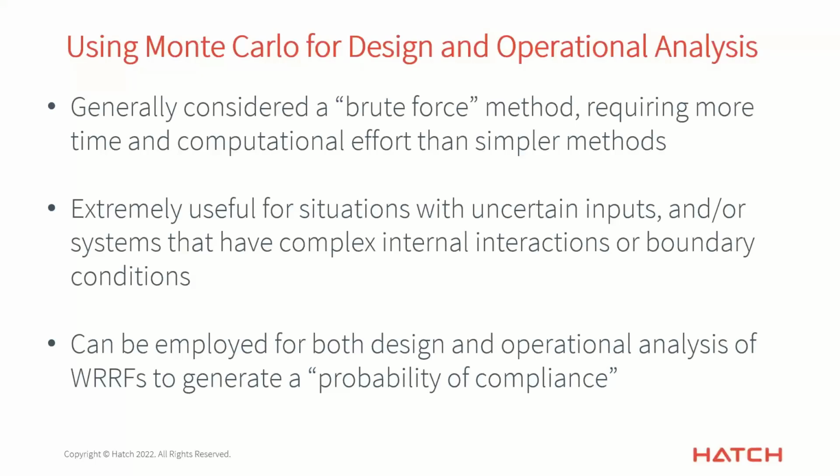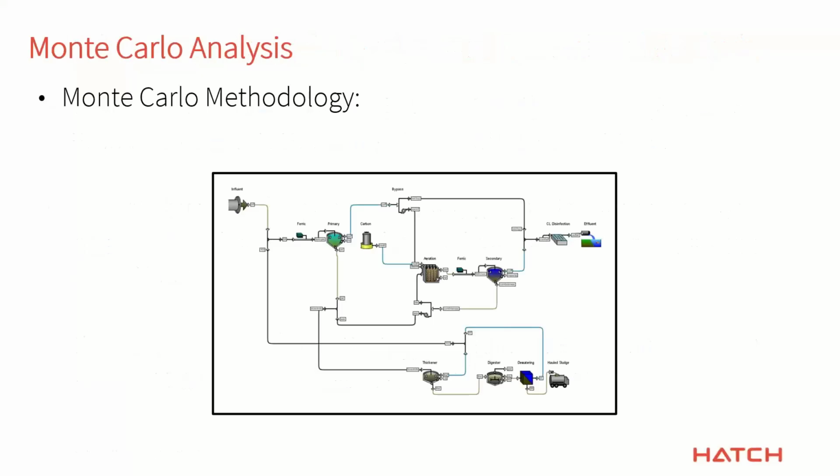And almost all of these types of analyses, to me, are interesting to look at from the point of view, and I know this is what our clients are doing, of looking at the effluent quality. What is the probability of compliance? So I ran 1,000 simulations, and I want to know what percentage of the time did I meet my effluent ammonia target.